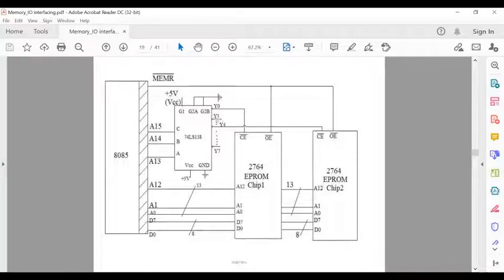Now, before going to connect this, you have to connect the enable input lines, because without these enable input lines this IC does not work properly and correctly. To make it functional, you first have to connect these enable input lines and give them the required power supply and the common signal.